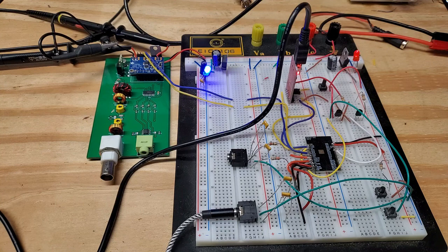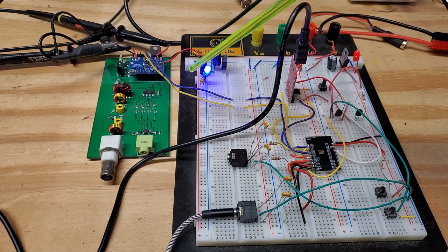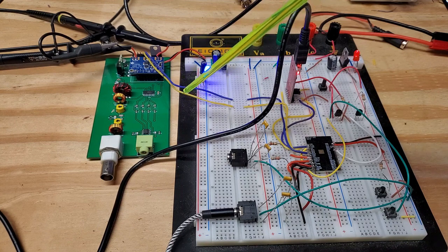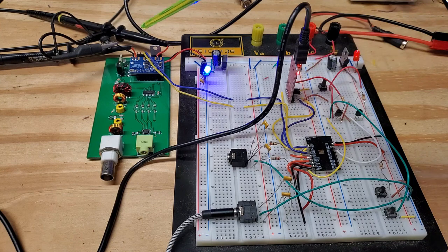Okay, so let's have a look at this. Let me try and draw some clarity for this rat's nest that I've got going on here. The SI5351 board is mounted on the Tayloe Detector board, and it's connected to the ESP32 through this purple and yellow line, which is the I2C control lines from the ESP32. The I2C is set up on pins 19 and 23 on the ESP32. I'm probing at clocks 0 and 2 here, and obviously there's power coming to this board through these lines here.